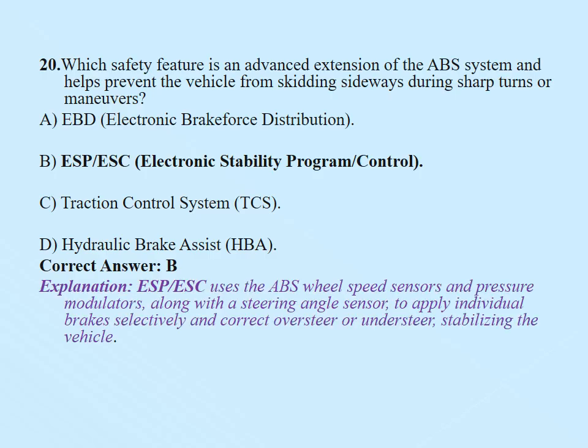Explanation: ESP and ESC use the ABS wheel speed sensors and pressure modulators along with a steering angle sensor to apply individual brakes selectively and correct oversteer or understeer, stabilizing the vehicle.